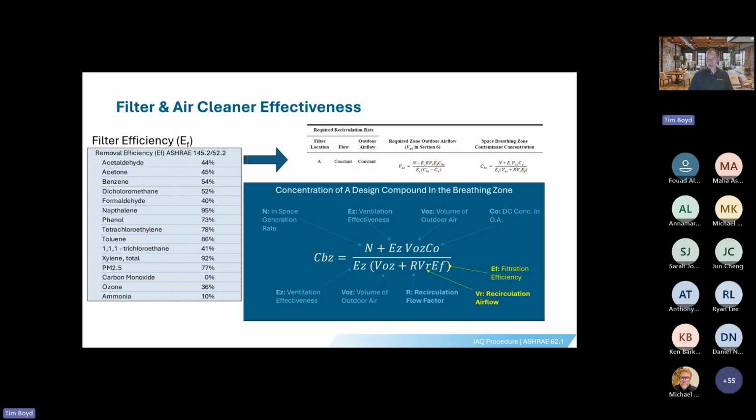This now highlights what I was talking about. So this is really the blow up, and this is for you. So when we send this to you, you can look at it and study it a little bit more. But just notice the recirculated airflow through the air cleaner plus the filter efficiency gives you what you're looking for. That's the fundamental change in the equation for managing what an air cleaner can do for managing the air quality.